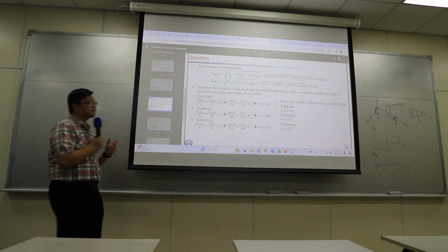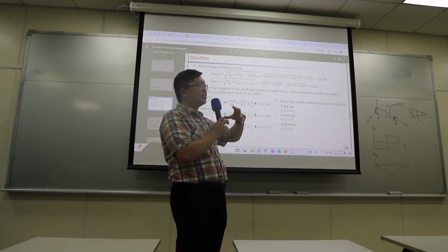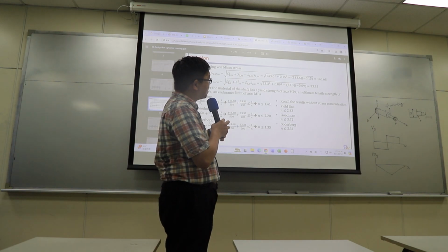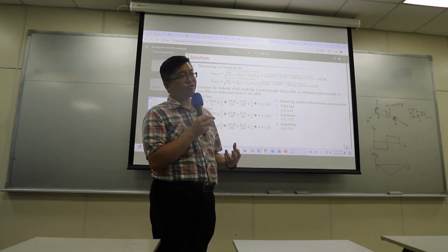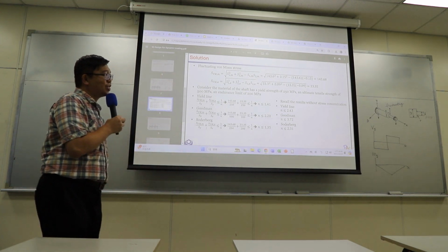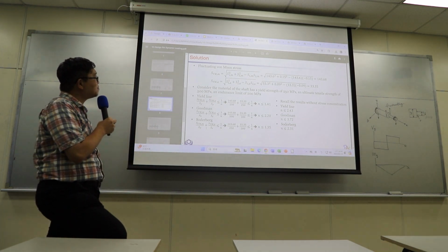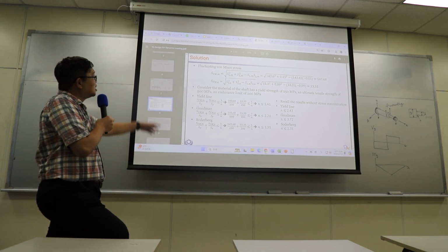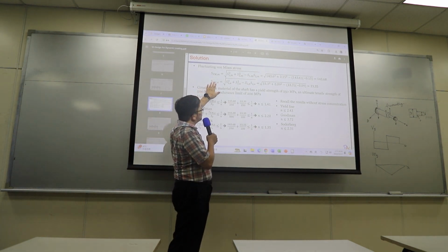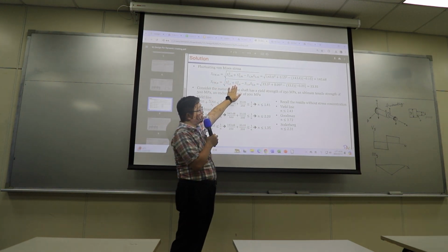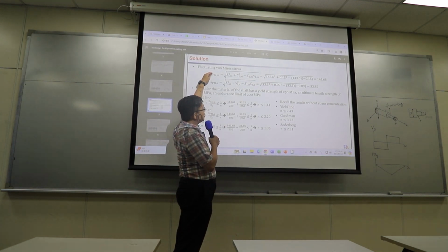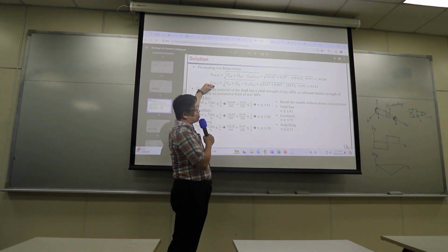And I like to give problems in cylindrical design because it's very commonly used in machines. So I think that tomorrow I will still use a shaft. So the von Mises stress, the equation for von Mises stress is right here. You need to figure out what's the mean value part, what's the amplitude part.